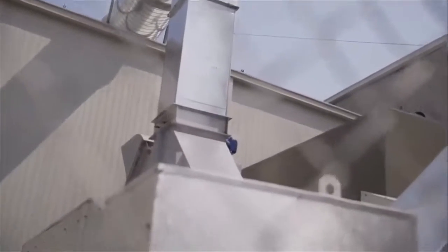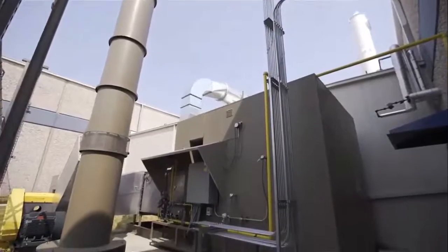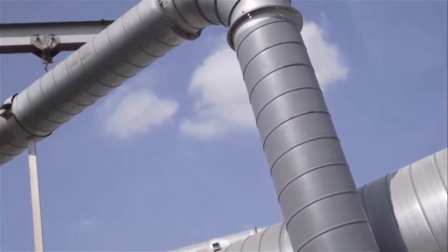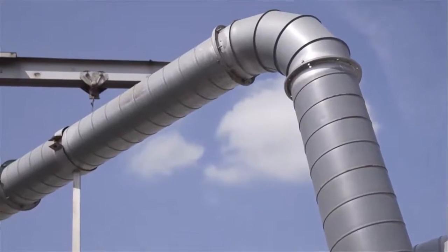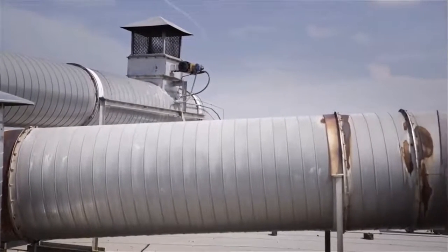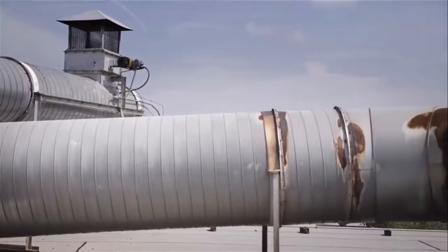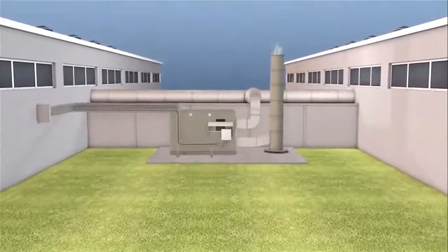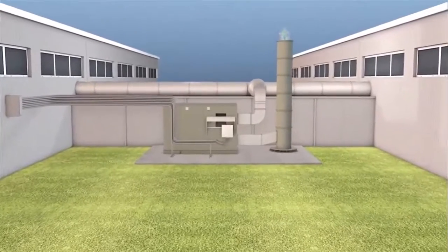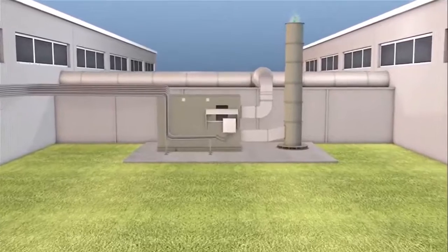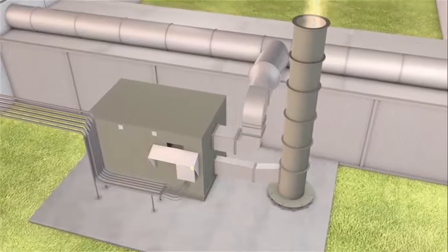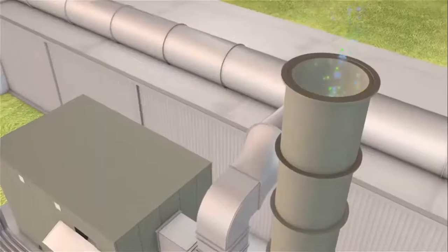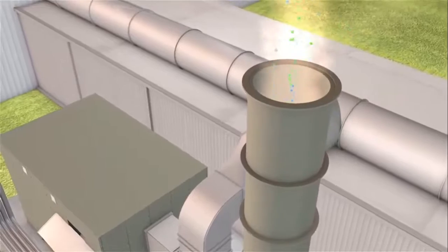A thermal oxidizer can be likened to a burner in a box. By burning or heating up the VOCs to a certain set point temperature, they are oxidized. This oxidation process breaks down the harmful particulates into carbon dioxide and water. Thermal oxidizers work well with applications where particulates may be present or have higher concentrations of VOCs. Also known as a fume incinerator, a thermal oxidizer, when designed properly, will treat a wide variety of process flow rates and VOC concentrations emitted from a facility.